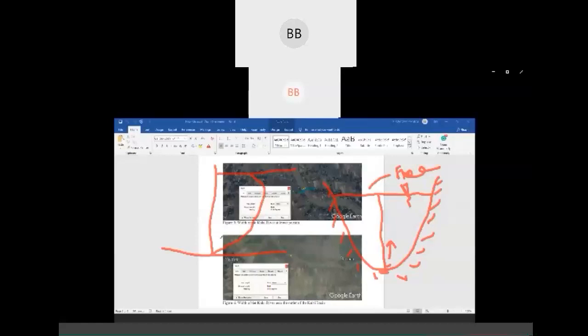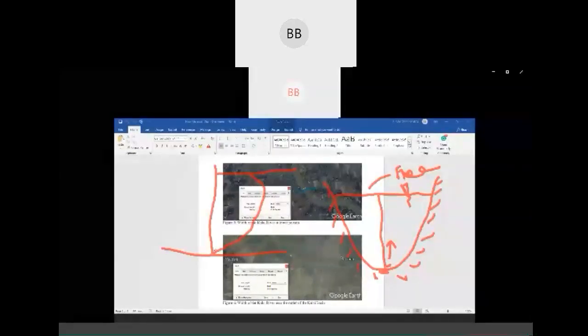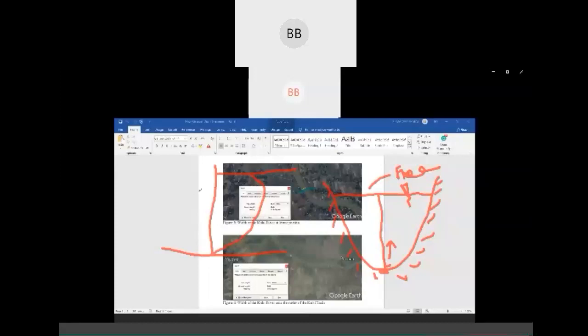We consider the velocity at the bottom to be zero, though it is not zero, but we consider it zero theoretically. Then when you go upward, if this is your y value, the depth of flow from the bottom of the channel, the velocity increases, and when it reaches the surface, due to the interaction between water and air, the velocity is reduced a bit.